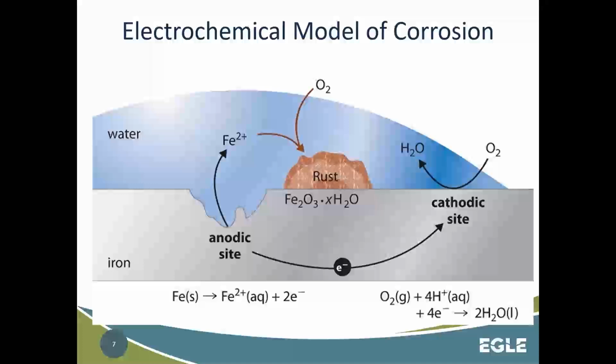Next is just a different look at what we just looked at. This time it's not a lead pipe, it's an iron pipe, but again, this just gives you a different look. So iron down here, you're having this anodic site and this cathodic site, maybe further downstream or even just the water itself. But again, that iron is being stripped away because you're having this chemical reaction with water. You're having this oxidation here. That iron is going away into this reduced state. It is no longer solid iron.